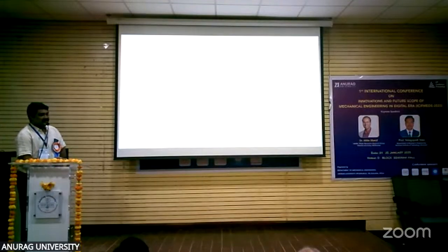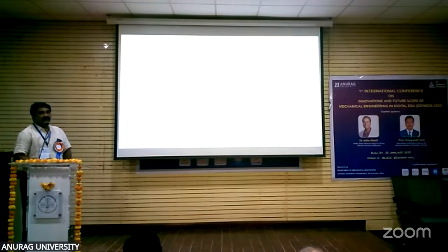And these are the conclusions. The joints with the square pin profile at 1350 rpm and 26 mm per minute had better tensile characteristics. The fine grains appear in the microstructure in the nugget zone, and the hardness values are highest in the S5 experiment.